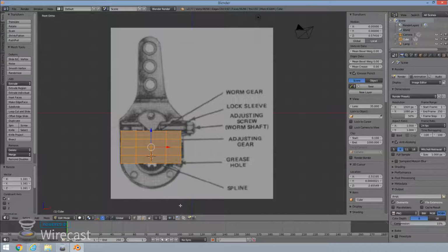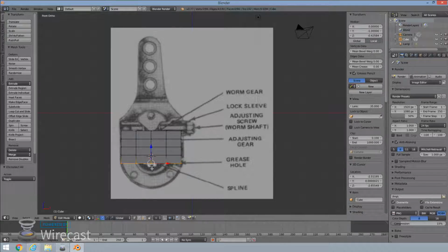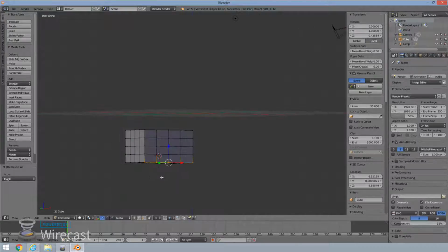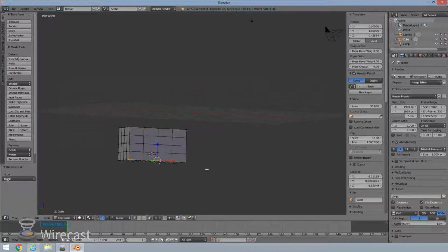Now, very importantly, when selecting vertices, and you want it to select the vertices at the back of the object, not just the front, as you can see, the ones we've selected right now, when I hit B and then drag my mouse button over it, I've got only the front vertices selected, but I want to make changes to everything, the whole square here.